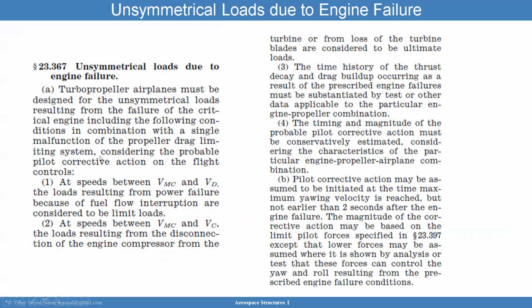Unsymmetric loads due to turbine failure need to be looked at carefully. I'll let you pause the video and look at this carefully, but you want to make sure that the timing and magnitude of the probable pilot corrective action must be conservatively established. And you want to make sure the time history of the thrust decay and drag buildup occurring as a result of prescribed engine failures must be substantiated. You want to make sure you can land, and that's the whole point of this. So I'll let you pause the video and read through this here, section 23.367.